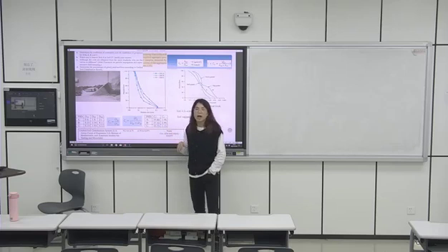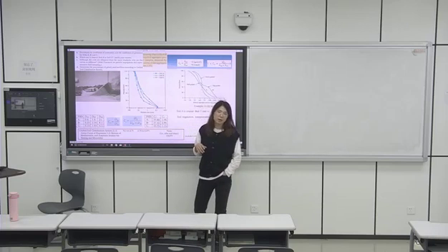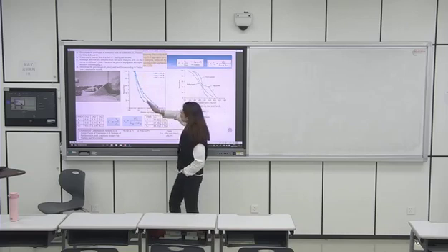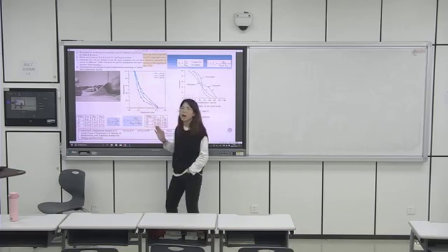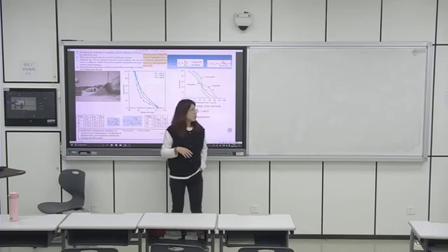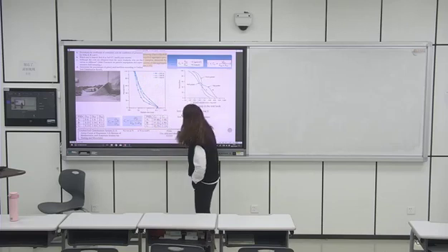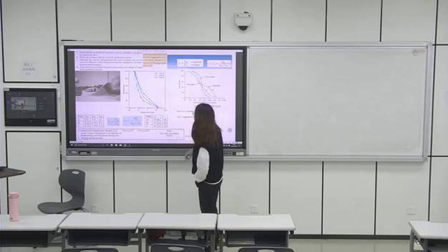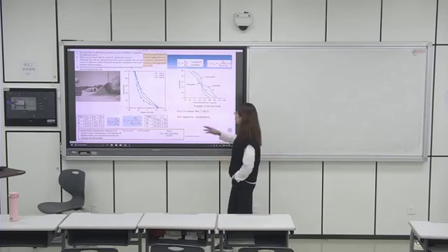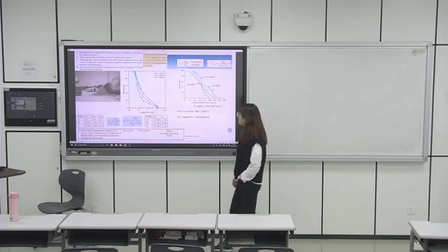That means soil A has more big particles, right? It's much coarser, right? That is, you see, soil A is more curved toward the big particle side. So it is coarser because it has more big particles. Then, apparently, if big particles mean coarser, then soil A is coarser than soil B.